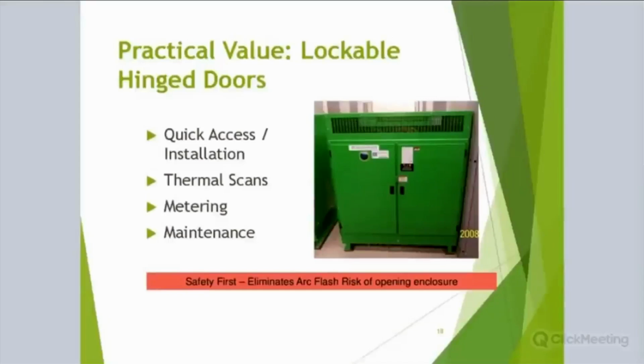One of the most beneficial options on a transformer that can be provided are hinged lockable doors. The reason being, if you have any issues with a transformer or fear you have issues and you need to thermally scan the transformer or possibly see what could be causing the added noise, and you have a trained professional or an electrician look at it, most transformers, they have to pull the front cover off, remove several screws, to get to the inside to see inside the transformer.